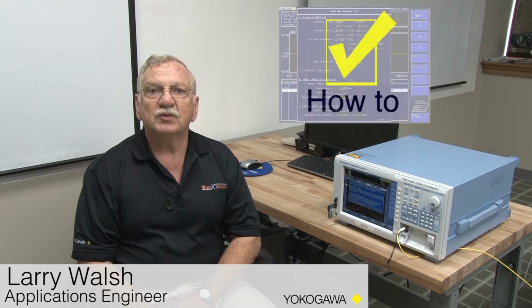Have you ever wanted to monitor your communications facility drift? That is drift of wavelength, amplitude, or signal-noise ratio? Well, now you can. What I am going to show you is a non-intrusive way of monitoring your network using an optical spectrum analyzer, OSA. You simply split a small portion of the light from your facility using a splitter and feed it to an OSA. Then program the OSA to monitor the facility and generate a log of its readings.